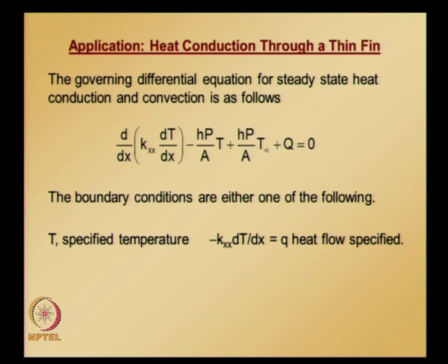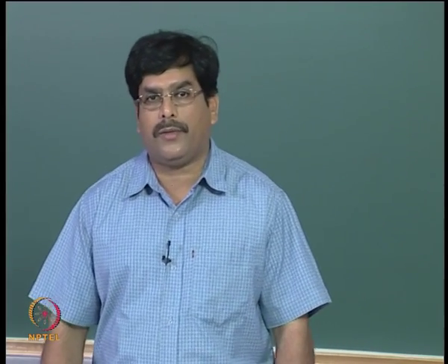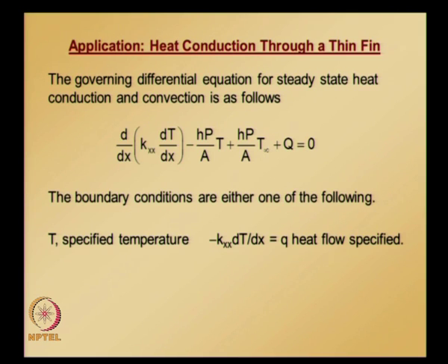And to develop the element equations, if you recall, what we did is we compared this differential equation corresponding to steady state heat conduction convection with the general one dimensional boundary value problem, and identified the corresponding coefficients. And once we identify the corresponding coefficients, we already have element equations for the general one dimensional boundary value problem. We can substitute the corresponding coefficients in those element equations to get element equations for this particular case of steady state heat conduction and convection.